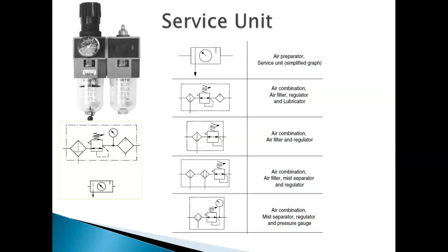We have several different ways that we do this. The first and foremost is we always have a secondary filter before you get to any components. Why? Because we want to filter out anything that might be in it. Water, dust, dirt, whatever, right? If it's gotten past the filter on the compressor, we don't want it in our system. Why? Because it messes up the seals on all your pieces, right? It can score. What do I mean by score?